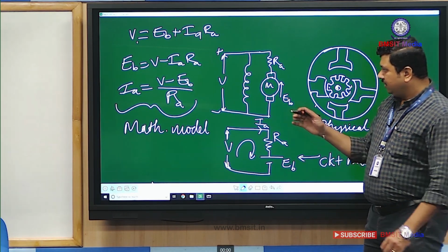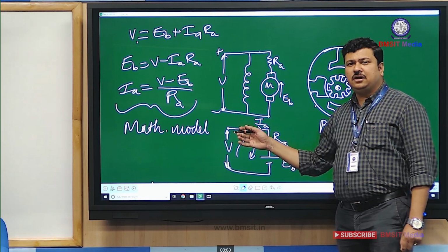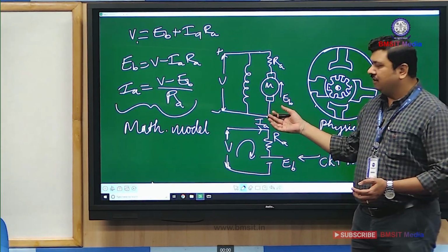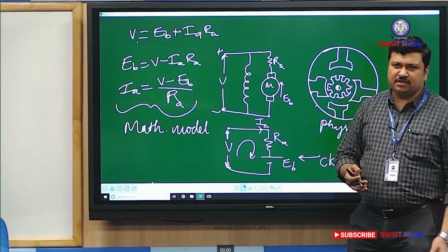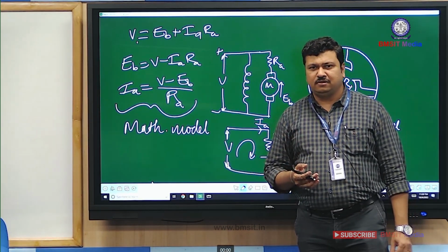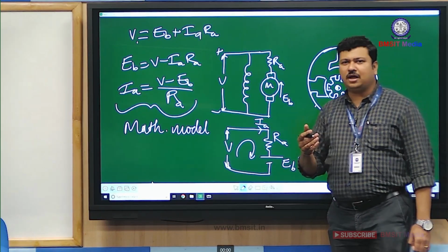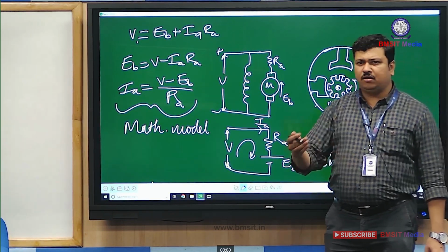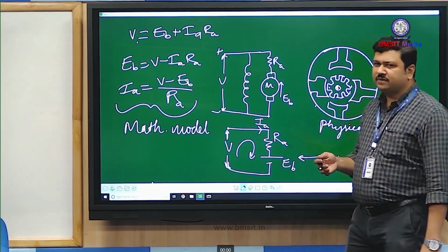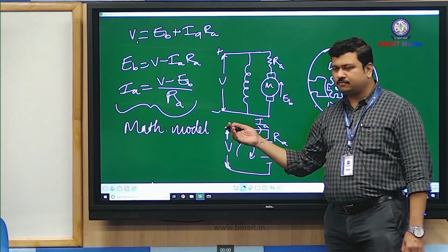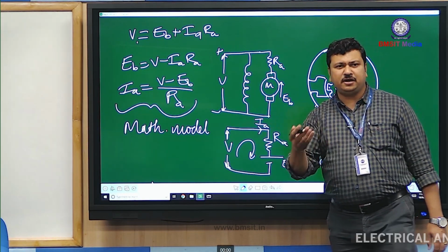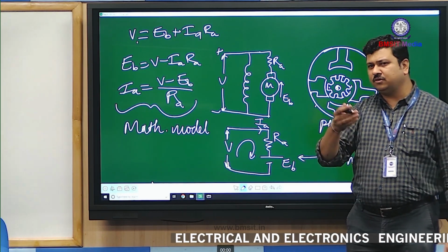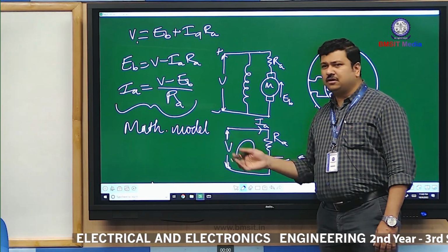And to do this analysis, I need certain mathematical tools. When I analyze the system using simple KVL KCL equations, I use matrices as my tool, or a system of linear equations where I solve simultaneous equations and get the variable values, and those variables represent either current or voltage. Likewise, I can use matrices in the form of Cramer's rule. Again, it is a system of linear equations. Both are linear algebra. Now, that is not sufficient for me.